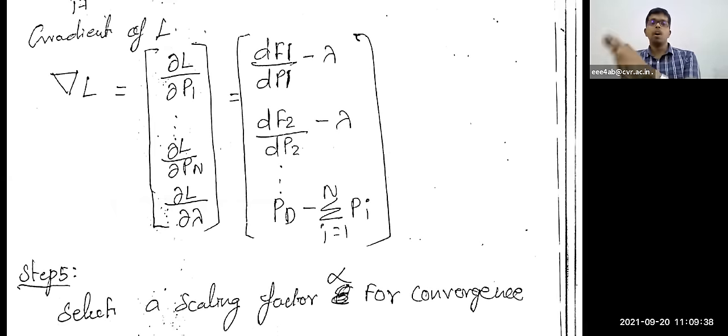First generating unit for how many hours? Then second for how many hours? Like that. So which are the least cost generators? I need only the least cost generator. If you select the costliest generator, then the amount involved in generation will increase. Again, the tariff to the consumers will be increasing. So it will be very easy to select the generating units and to run them for particular hours of time, everything.